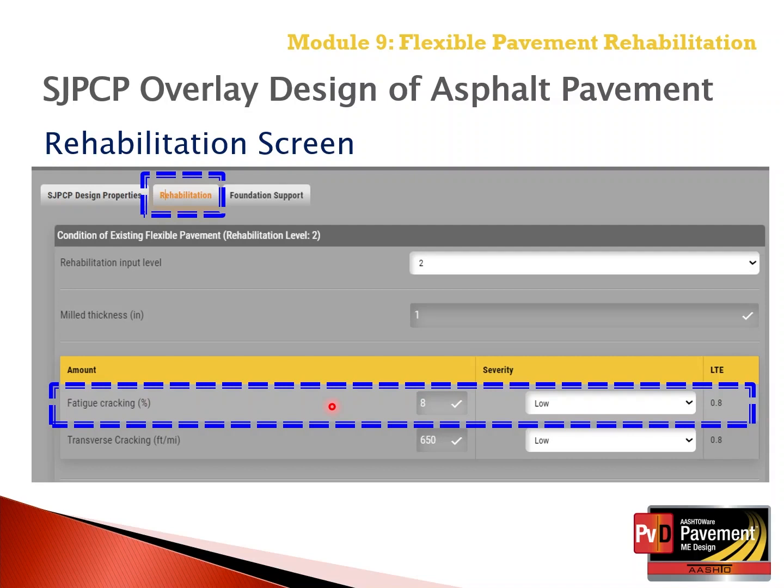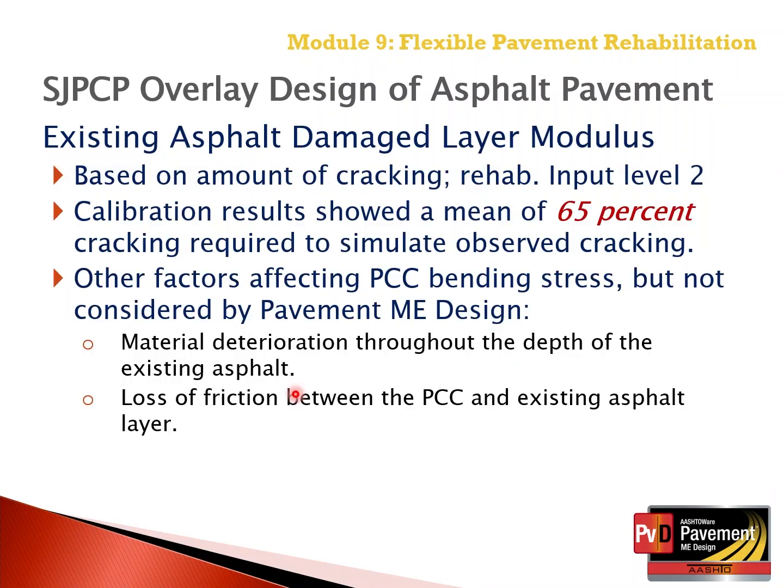So the user can enter total amount of bottom-up fatigue cracks in the existing asphalt, but the program uses a constant value for bottom-up fatigue cracks. And so that is based on the amount of cracking, rehab input level 2, and the percent of 65% cracking was derived from calibration